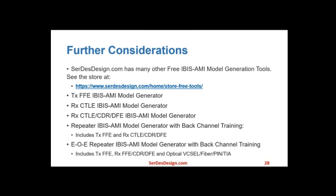There's a repeater model generator that includes back channel training with the transmit and receive generators. And there's an electrical repeater that also includes back channel training, which includes not only the transmit and receive portions, but also an optical VCSEL fiber PIN and TIA generator.